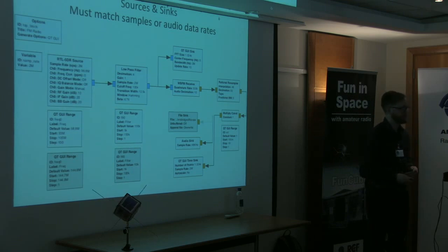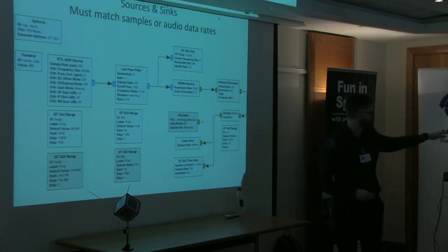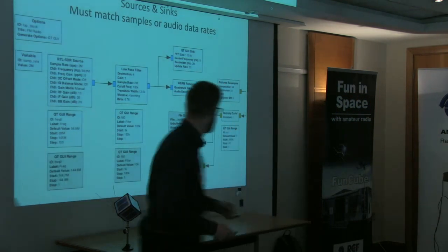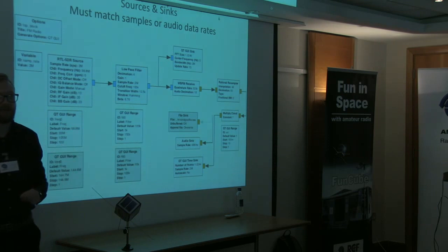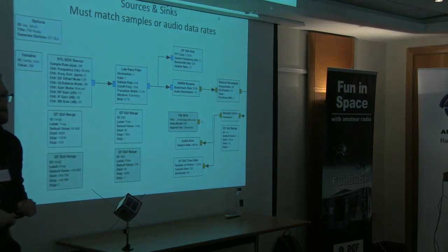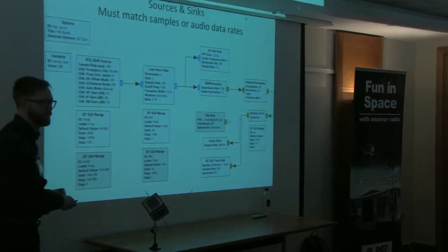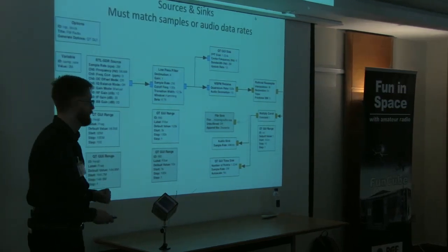managing this whole chain. So let's just kind of start from this particular system, an RTL dongle, on this side. I'm sampling at 2 meg, and eventually, if I want to hear some FM, I've got to come all the way right down to what my speaker's going to be outputting. Okay? In our case, I think I'm using 44.1 kilohertz.